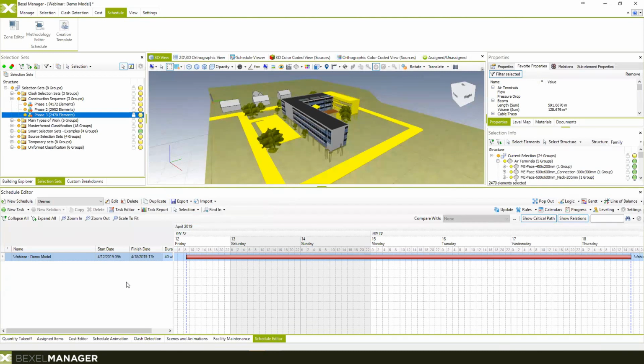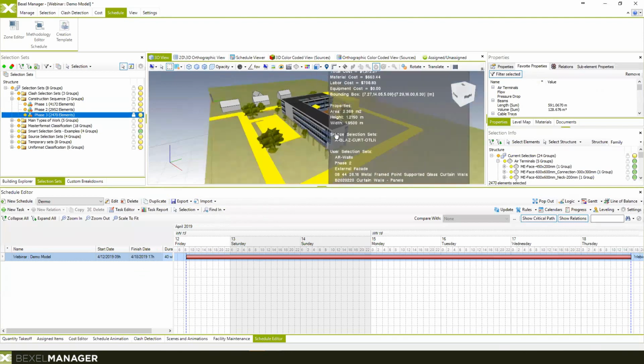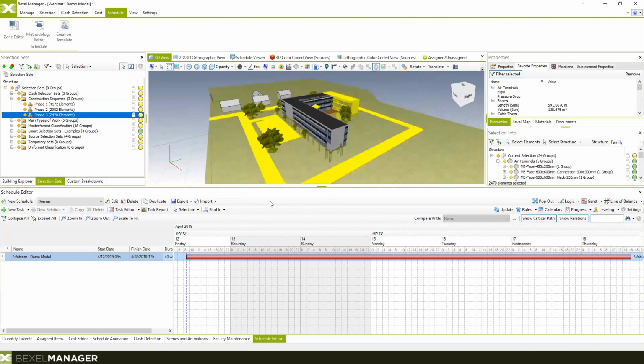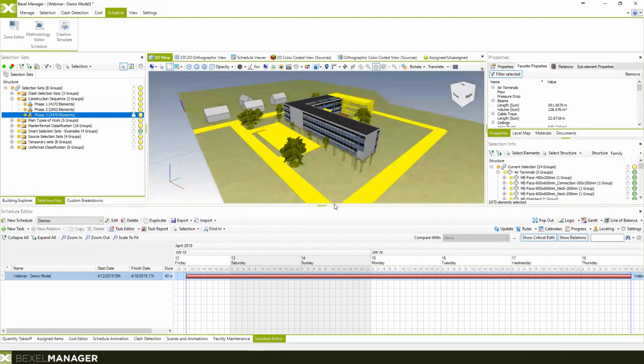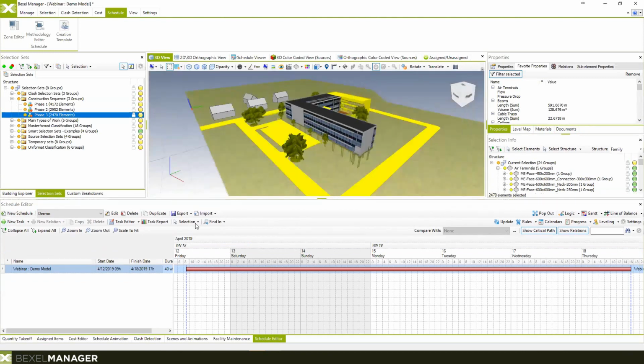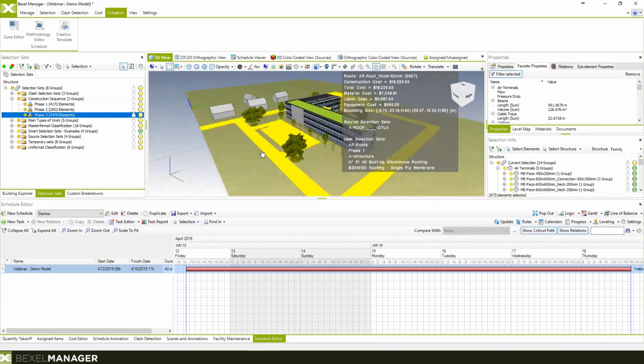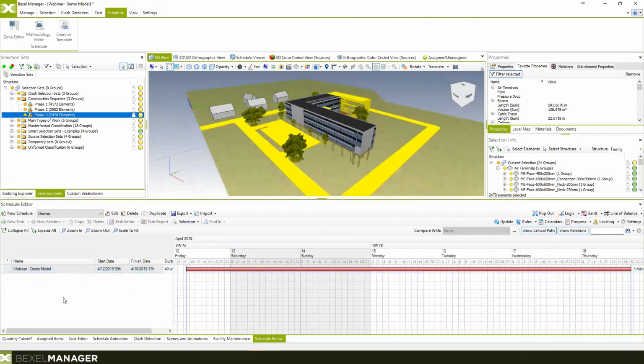But in that case, and that's a really time-consuming process, you're going to have to link manually or semi-automatically all these 3D elements with the activities of your imported schedule. And that's almost the same manner as the other 4D simulation BIM software actually works. They import some schedule and they manually link 3D elements to the activities that are already imported from your schedule from somewhere else.